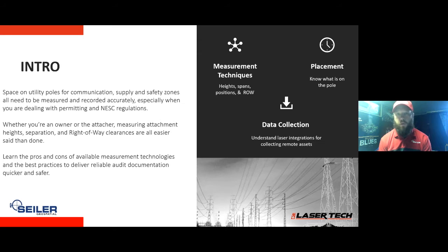How many years are they actually going to go out there and do a pole audit for ours? Because the one that I worked on, my last job that I worked on, it took us 2.5 years to do about 250,000 poles. So it definitely does take a while, especially when you're needing to get hands up, but they'll do it for rent purposes. Who's attached to the pole? Is the pole even good? There's hammer tests that they do to make sure that the pole is still good. And then there's even pole loading to make sure that they can actually attach any type of new attachments to the pole too.